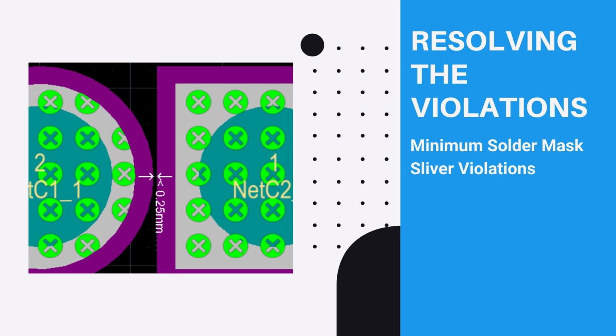To allow for layer alignment issues, the mask openings are typically larger than the pads, reflected by 4 mil or 0.1 millimeter, which is the expansion value used in the default design rule. Now, there are other techniques for applying solder mask, which offer higher quality layer registration and more accurate shape definition. If these techniques are used, the solder mask expansion can be smaller or even zero. Reducing the mask opening reduces the chance of having solder mask slivers or silk to solder mask clearance errors.